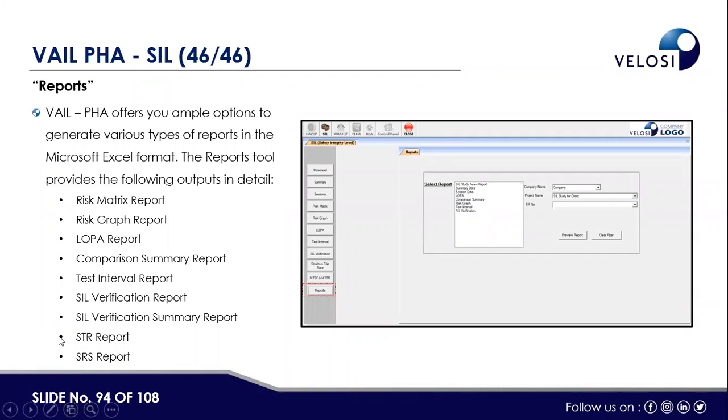For example, if we want to check by utilizing the risk matrix approach what the SIL level is, by the risk graph approach what the SIL level is, by LOPA what the SIL level is, we can make a summary as well. And then the test interval report as well as the SIL verification report, SIL verification summary sheet. We can also generate STR reports and SRS reports as well.